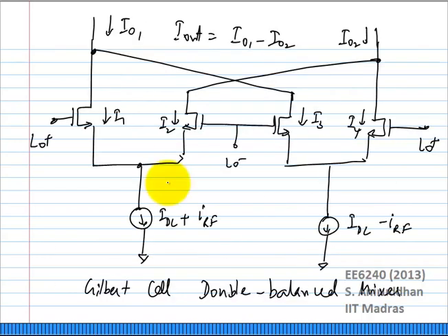How do you generate this? Again, just even a simple transconductor may be good enough. Any kind of V2I converter will do. A MOSFET is a simple transconductor, but you can have degenerated, you can have other ways of performing the V2I conversion. All of those things may be applicable. However, if you choose a very complex one, you do have a headroom issue, because the way you are multiplying the two signals is by stacking them up between supply and ground. Okay? If you have too many devices stacked up, you may not be able to operate it at a very low voltage.